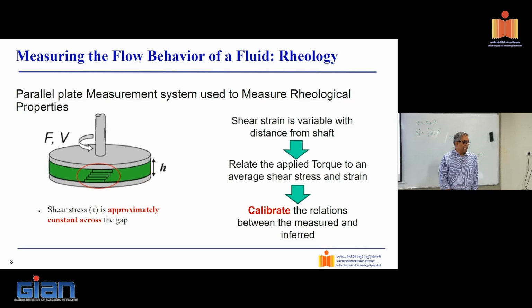If you do not do that, right, what you'll end up with is this. And when you're doing rheological measurements, it's perfectly all right to report torque and rotation. You can certainly report those. The only problem is that every time we do some measurement, we expect to see shear stress and strain rate, and that relates to viscosity. Okay, so some of the purists who actually do rheological measurements don't report shear stress and strain rate from something like a parallel plate. They'll simply report torque and rotation values.